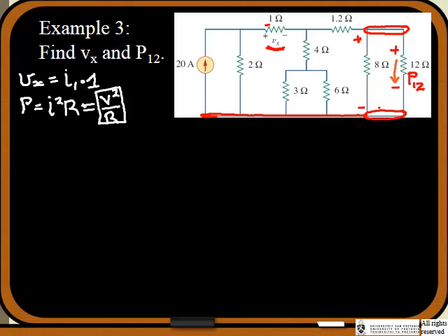How are we going to start? Since for now I don't need any of these circuit components, we are going to simplify that part of the circuit starting from the right and simplifying it as we go inwards. Our first order of business is going to be the two parallel resistors, the 8 ohms and the 12 ohms.